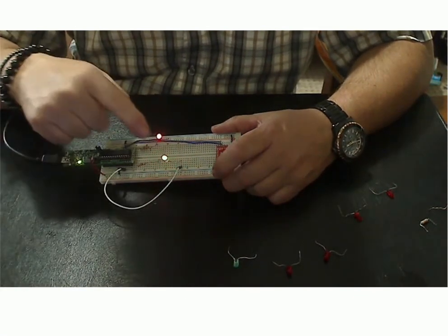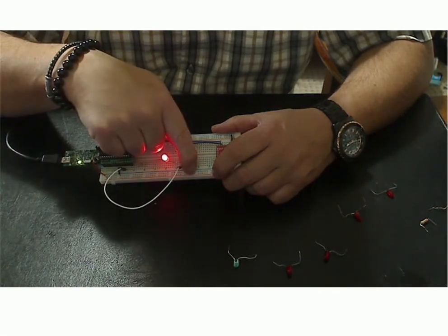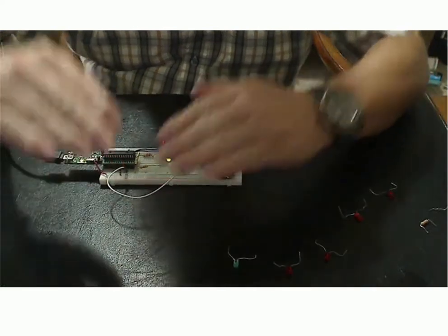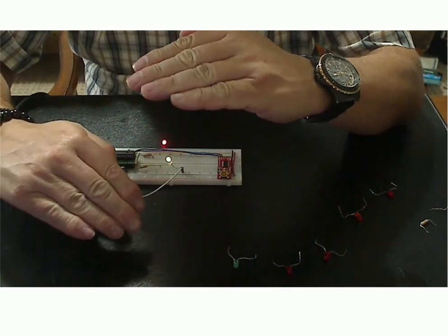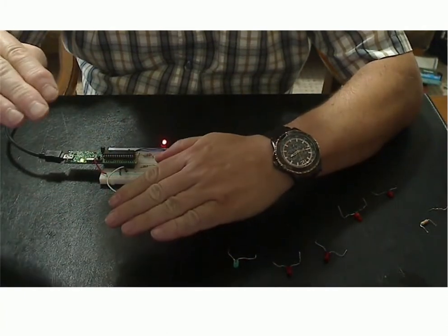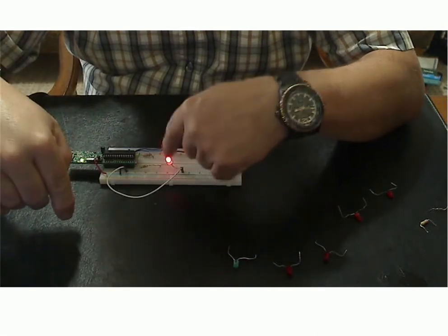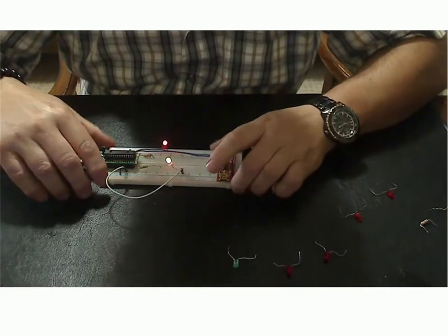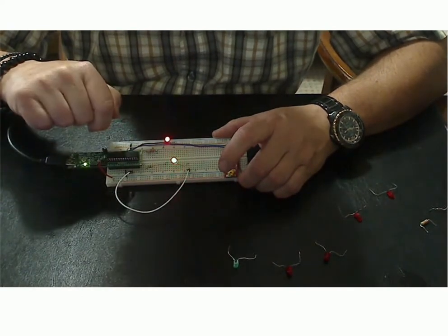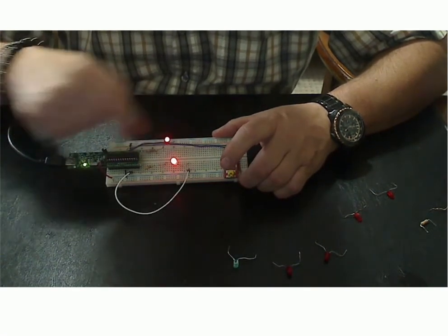With something like a bicolor, one pin would only give me one color, but by having two pins, I can play with those pins. I can make one pin high and one pin low. The current will flow from high to low and turn on one color. Then I can flip which one is high and which one is low. Current goes the opposite way through the LED and the other color comes on. So in the next section of this video, we'll learn how to program the PIC so that we get these behaviors.